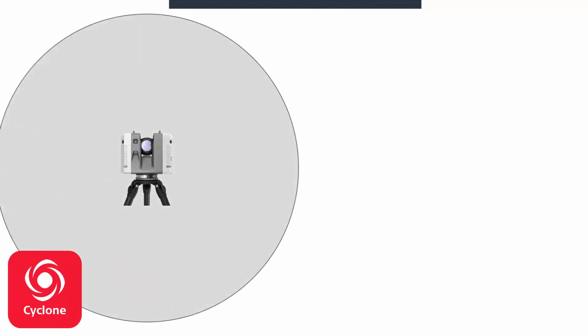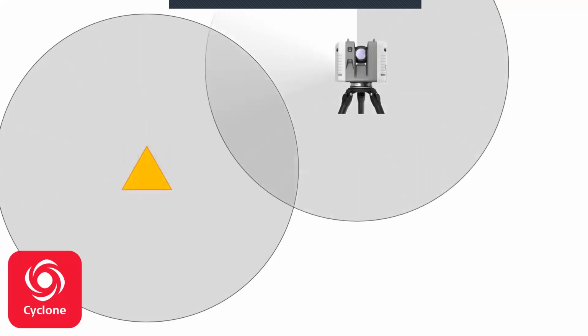When you use a scanner, we put one scan in one place to capture, and then we have to put it in a second place to have the second image, because the whole building cannot be captured in one image. Suppose you have a big floor or you have to capture a building and the area around it. We put the scanner at various positions and then merge the data. This is like Google Street View, where you jump from one place to another to rotate and see again.